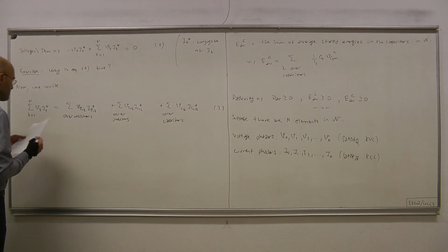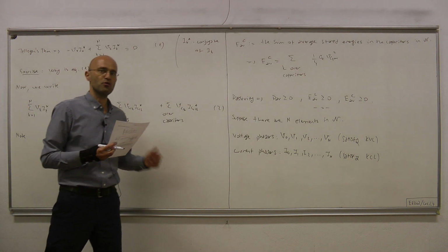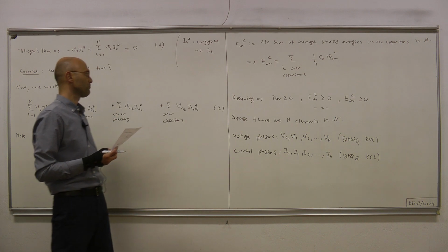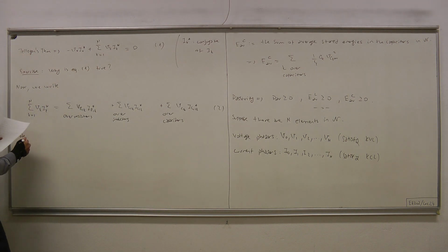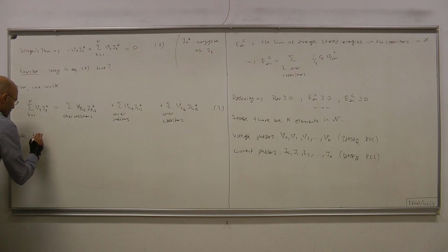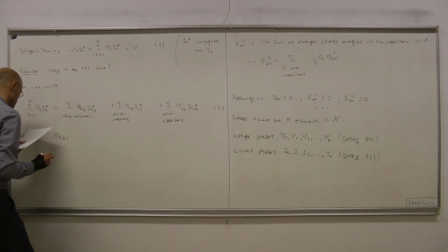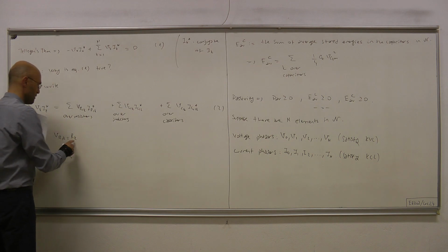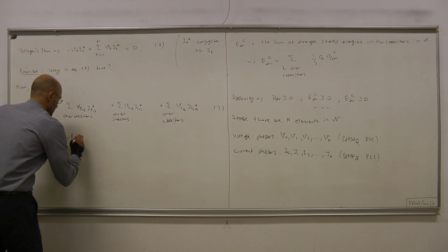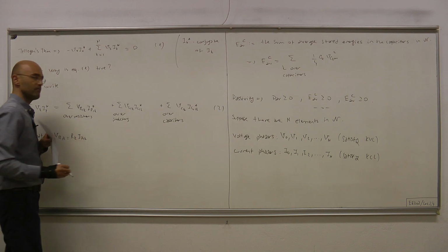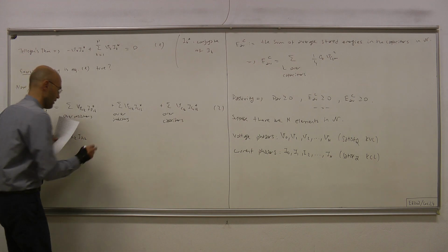And finally, let's express voltages in terms of currents, or for the capacitor, current in terms of the voltage, which we can do easily. In other words, we have VRk equals Rk, the resistance of the kth resistor, times IRk. Voltage equals resistance times the current phasor.